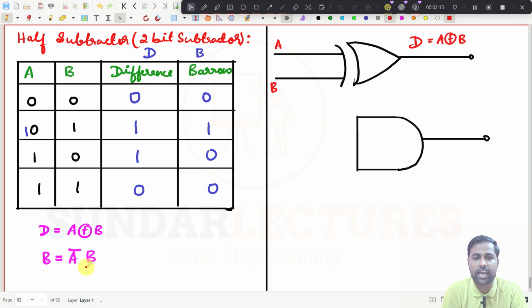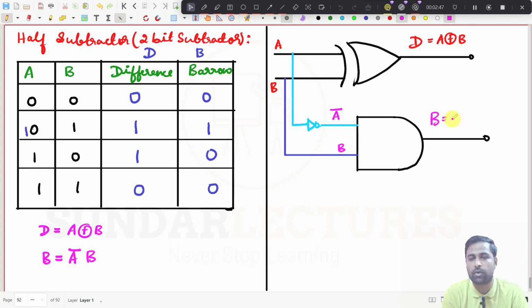And now what is this one now? A bar into B, right? So what I need to do here, I have to take this A and I have to put a NOT gate here so that it becomes now A bar. Simply, right? So now I got A bar, and what is the next one? I need to give this one to here. This is now B. So what will be the output equation now? So this becomes now A bar and this becomes now B, right? So simply, the borrow should be equal to A bar B. That's all. Now this is the diagram for the half subtractor.